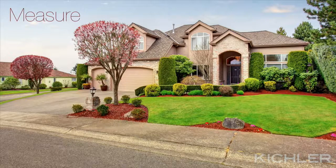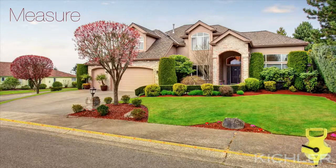The quick and easy way to create a scale drawing of a small to medium-sized property is to place a 200-foot long measuring tape along the curb and walk from one end of the property to the other, noting the distances of major points of interest as you walk. Include the edges of the house, driveway, trees, etc. You can then do the same thing along the side of the property to get a scale plan of the